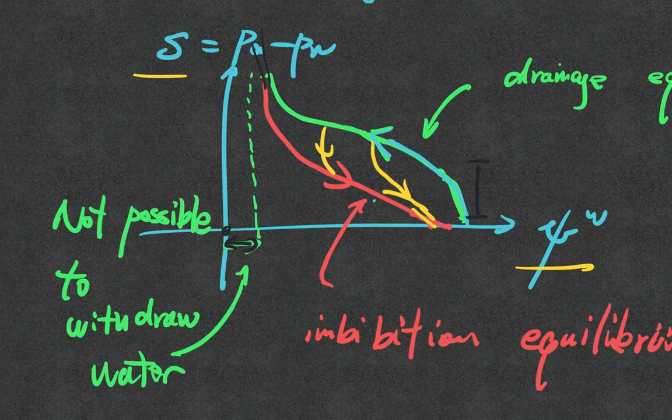Then what would happen is that you would have not-a-number calculations, and that is due to the fact that your model is not initialized properly. If you want to model the unsaturated one, make sure that the curve starts somewhere here, but not actually here. This is a common mistake people make. You start from here, it won't work. Or going the other way to the infinite point, it also won't work. Make sure you set up the initial state at equilibrium. That will require some calculations.